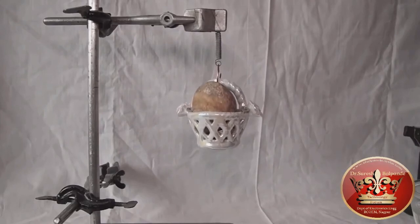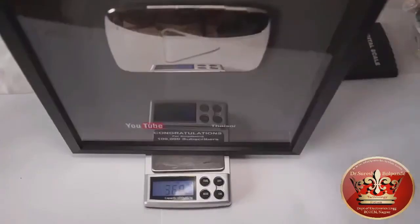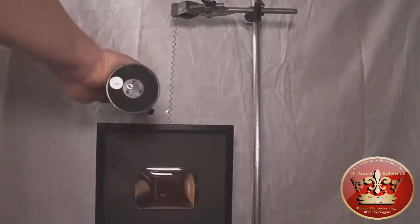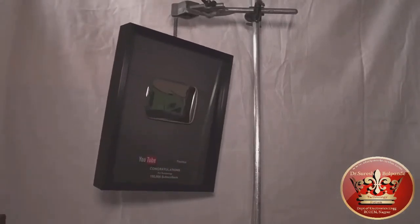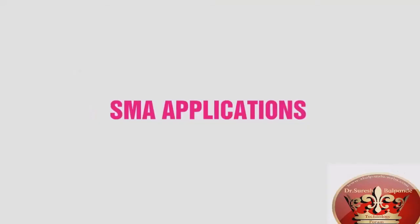In order to see how big the power is that Nitinol creates when restoring its form, I hung a silver button on a spring, which weighs about 1 kilogram. Trying again with heating the Nitinol, and what we see is even this huge weight can be raised by the spring very easily. However, you could now probably ask,